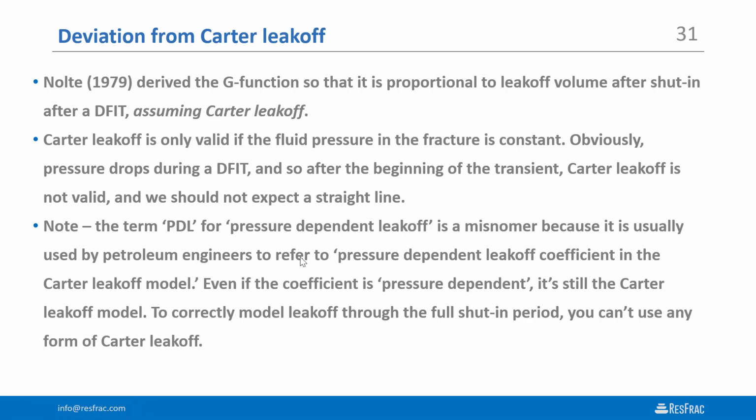It's not what I mean, which is if you actually just rigorously solve the flow equations, you don't get anything like Carter leak-off at all. So you can't merely make the Carter leak-off coefficient dependent on pressure and say, oh, we've handled pressure dependence. It's completely different. You can't use Carter leak-off at all in any form to model the full shut-in period. You have to do a more general mathematical solution. And that's not news, by the way. Of course, Mayerhofer wrote some great papers in the 90s talking about that and developing techniques around that. So this is not a new idea, obviously.